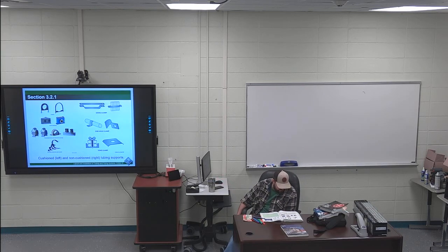Page 36, sentence that splits the columns is highlighted. Many times the tubing will share the same tray with instrument cable and be divided from the cable by a partition in the tray. You have to have a cable partition if you're running instrument lines as well as instrument cabling in a cable tray assembly.